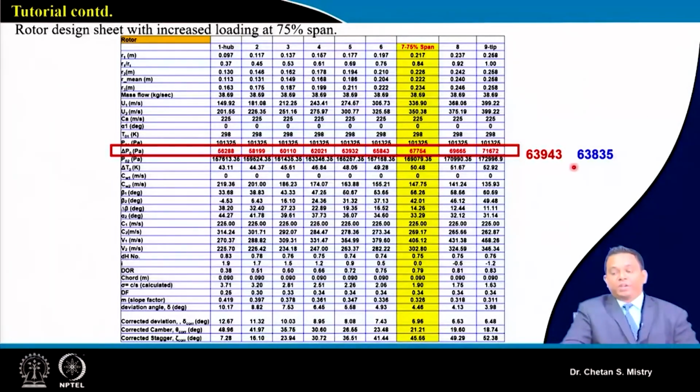So what we are expecting in the sense of pressure rise is 1.63, this is the total pressure rise we are expected to get. Okay, and based on the modified version at mid span, we have modified our delta P0. This is what represents the distribution of delta P0. When we did the design for the subsonic compressor, at that time we also discussed the same approach. So in line with that, this is what we are discussing here.